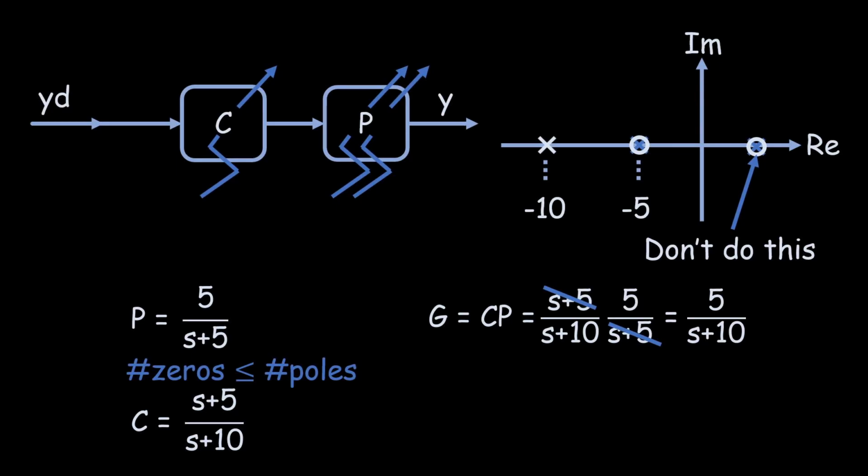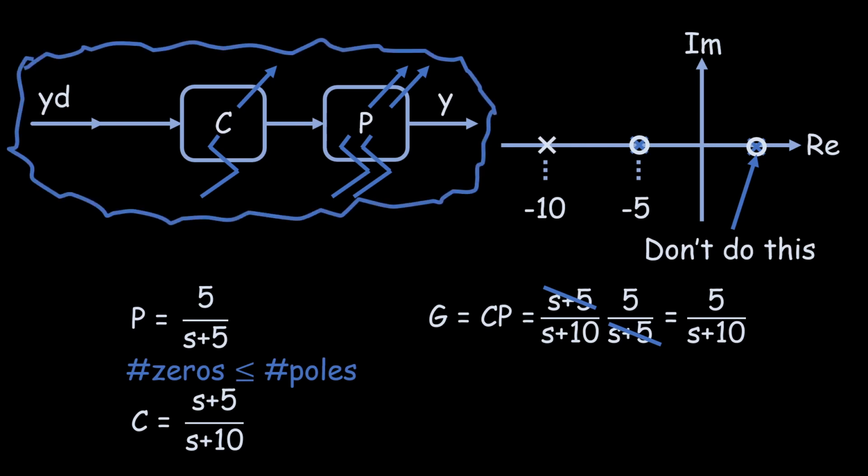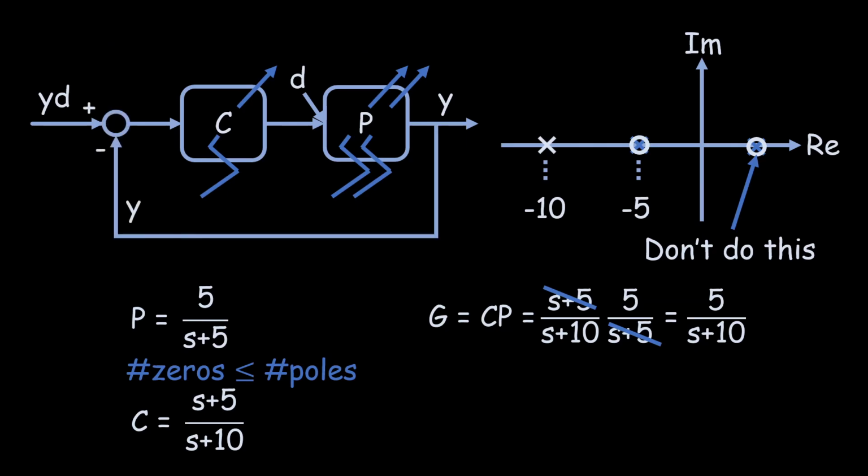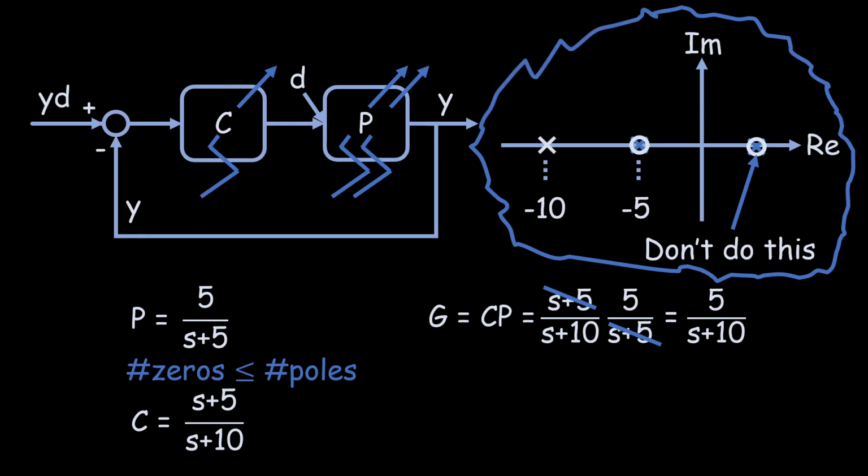Moreover, if you pay attention, you'll notice that the representation is the open-loop representation, which means that if the system suffers from external disturbances, the open loop cannot make corrections. Therefore, in most cases, we design in the closed loop. There are two methods. The first is to design the controller using methods like root locus. The second method, which we will introduce today, is the equation-solving method.